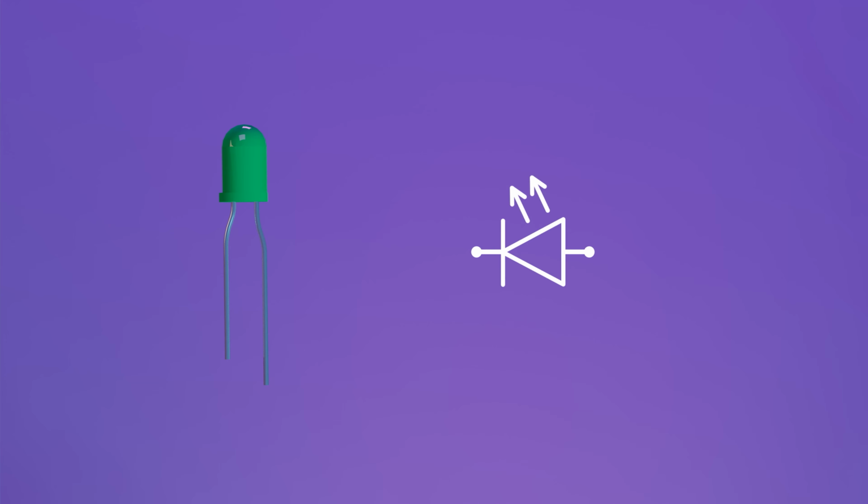To connect to the network, the LED has two outputs, anode and cathode. They determine the direction of the DC current, so if they are connected incorrectly, the DC current will not pass and the LED will not light up.